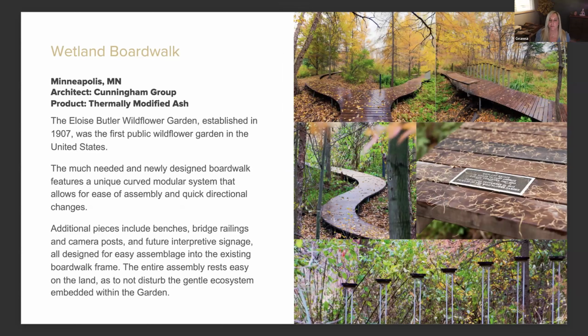Thermally modified wood is great for boardwalks because it's hydrophobic. It's absorbing a lot less moisture. It's not going to react to huge temperature swings. So in a lot of humid areas, you're seeing elevated decks, you're seeing a lot of boardwalks, you're seeing a lot of terminals in the Pacific Northwest. They love the thermally modified ash because it is such a hard, dense wood. And again, no maintenance, just let it weather.